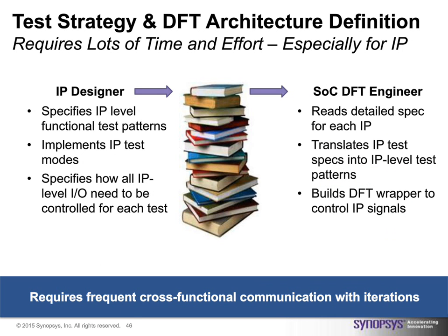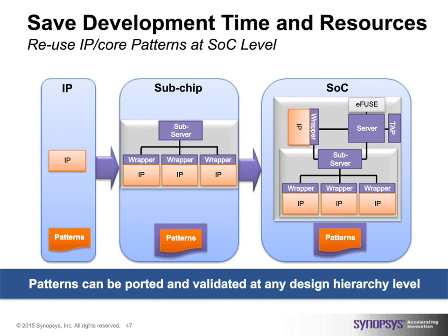It will take an IP with its patterns and, from one level to the next, from an IP level to the subchip level, create the access and interface, and build up the patterns at the next level. Same thing from a subchip to an SoC, again carrying the access as well as the patterns together to the next level. So SHS, this purple part of the diagram, allows us to build it up and connect it with the memory solution for FinFET that we have shown earlier. Of course, there's much more detail on those things. Today I'm just mentioning them under this umbrella.